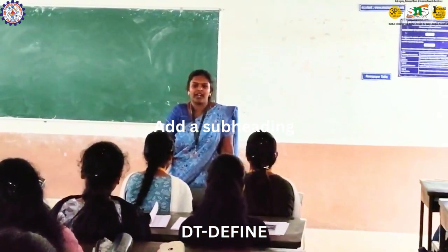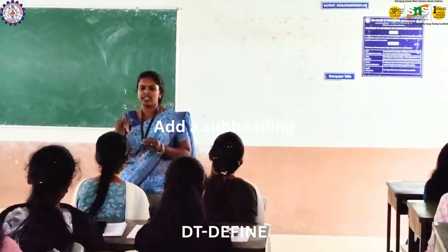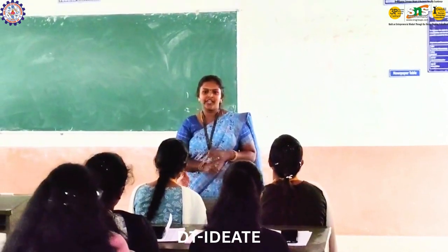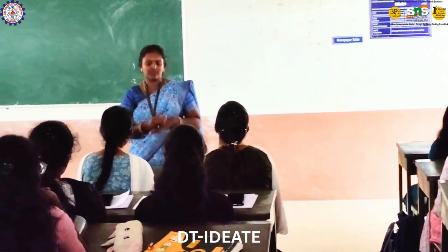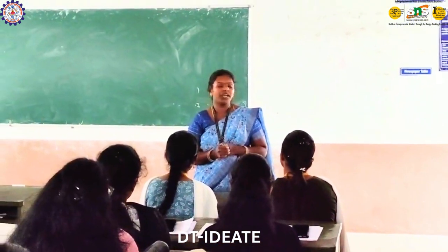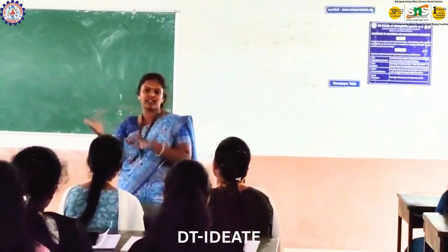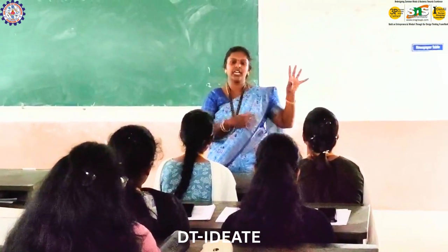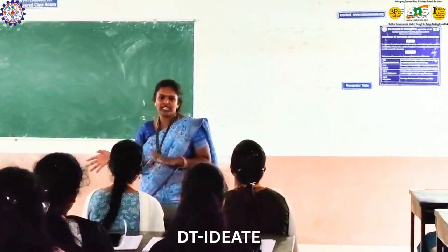So next stage is define part. So define part means the multiple solutions. So what will we define the stages define part? So in previous empathy stages, we were struggling with accuracy, right? So in this define part, we have 3 types, that is full wave, half wave and bridge wave rectifiers. So these rectifiers is used in DC power supply. And next application is our mobile phone charger. So mobile phone chargers means it will take 230 volts and it will be converted to 5 volt power, right? So the crucial role of rectifier is converting that particular AC, that high voltage of particular AC signal is converted to 5 volt DC signal, right?